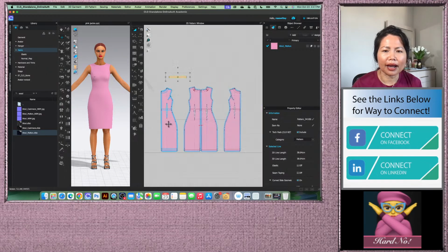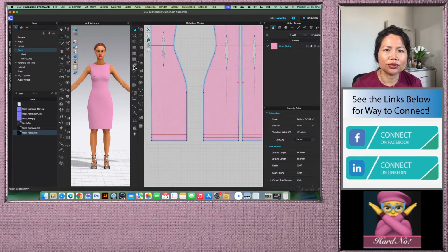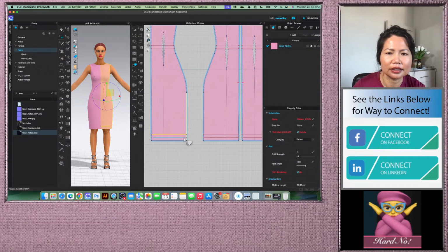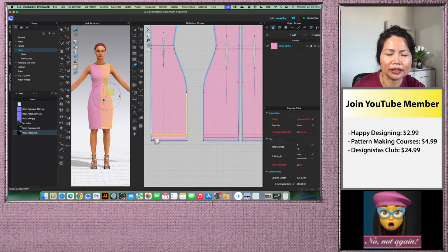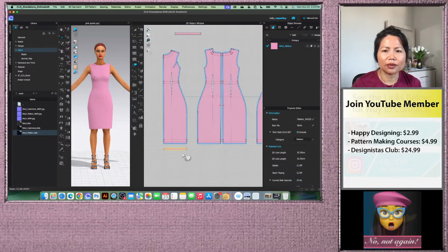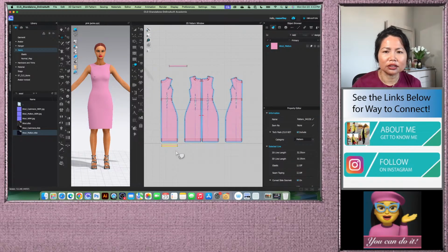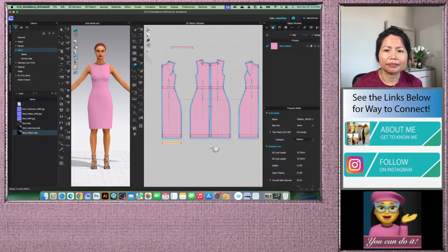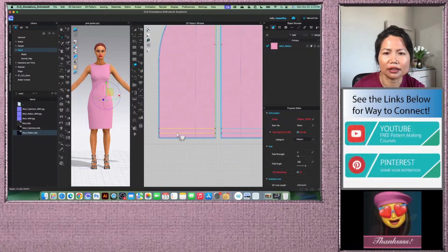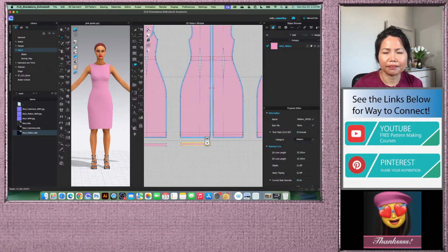So how about create pattern? I can actually use the trace tool here. Click on this line, click on this right here, right click, and then trace as pattern, and then I can simply click one right here to place. So now we create this pattern, and we can just change the color to black, and we'll do the same here. Click right there, right here, right click, and then select trace as pattern, and right there. Okay,